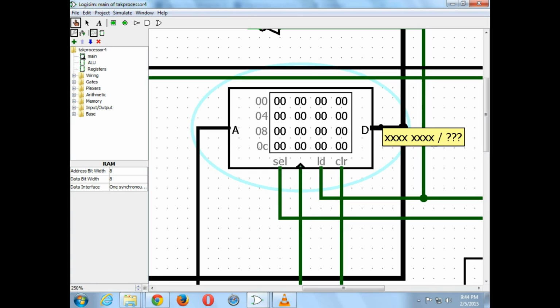So the processor now has to drive not only the address bus but also the data bus, and then it will put a 0 to the load line, because load is 1, store is 0. Store is from the perspective of the RAM chip. You're storing the content. You're overwriting the content of a location.